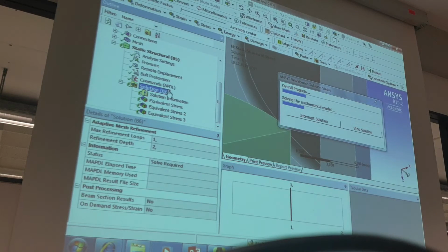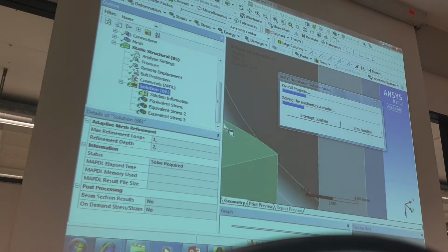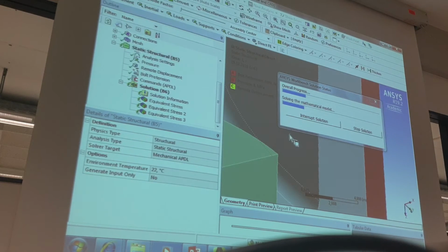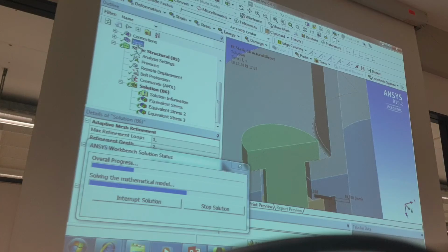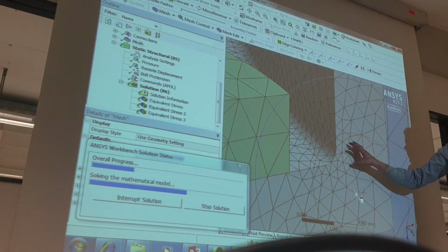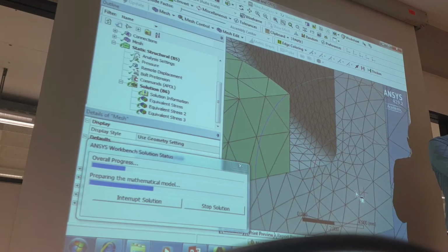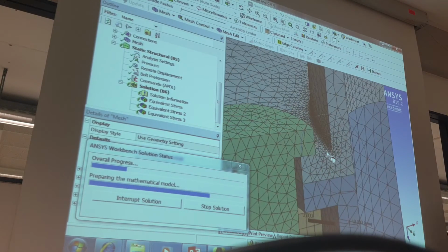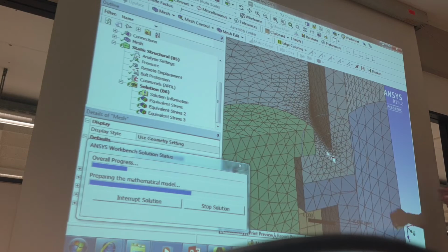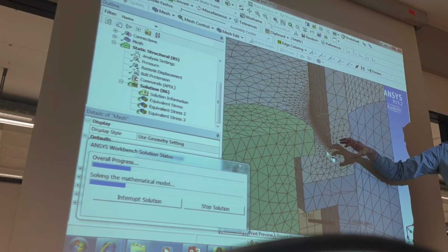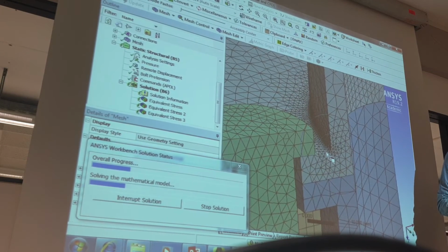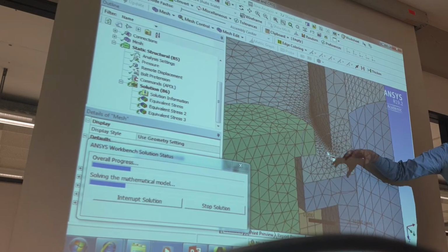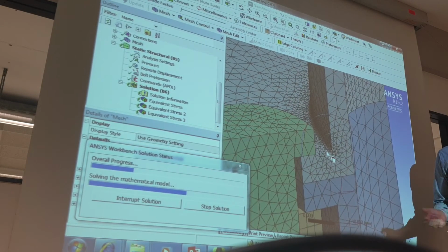Okay, now we will check whether it is quick or not. This is the first thing. And the second thing, also very important: we spoke about these basis functions, yes? Many people forget that we have basis functions for interpolation, that every element is interpolated inside with these basis functions. And only one rule: define it exactly. You need to refine places where you need the solution. With this idea, we can say we need better basis functions in the places where we need the solution, and not so good basis functions in the places where we don't need it.